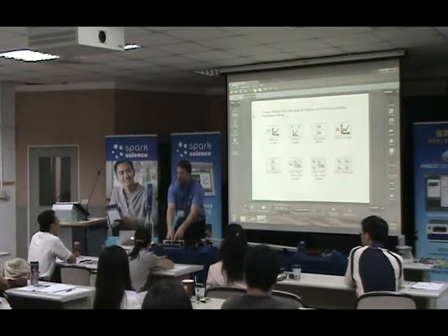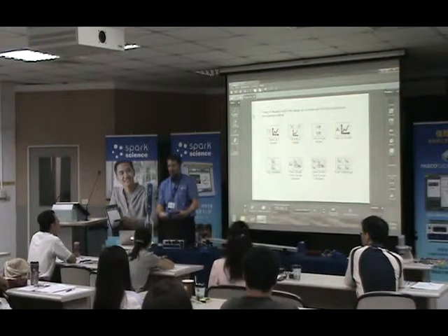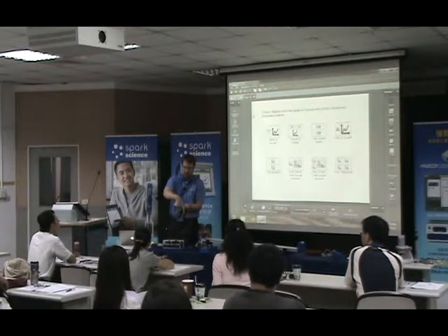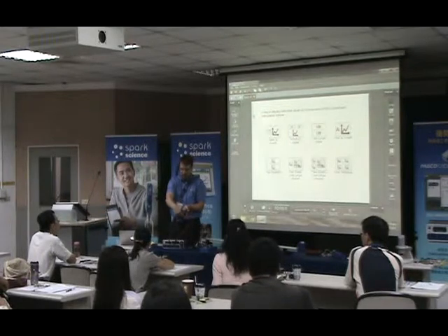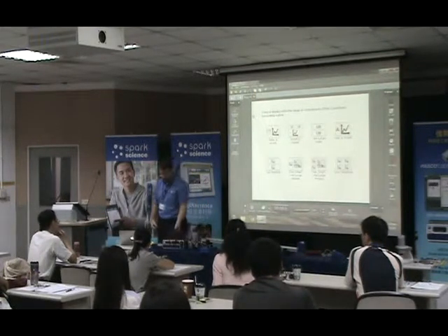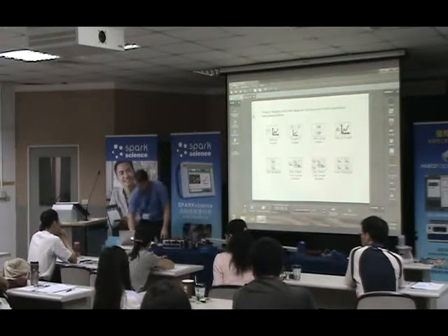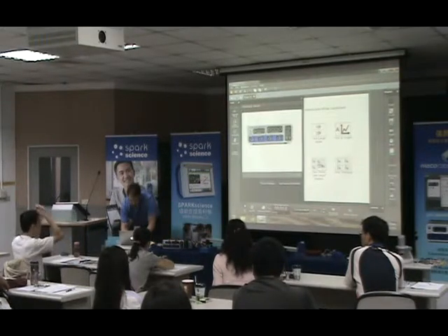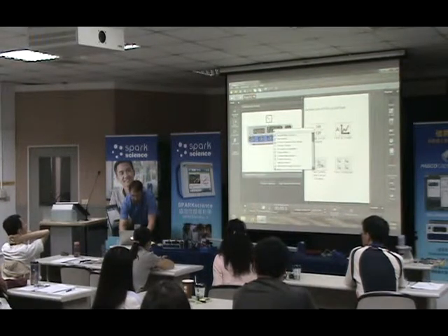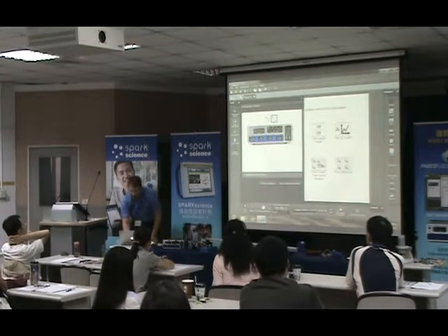And then these two things are voltage sensors. So I'm going to be measuring two voltages. One is going to be my source voltage across the whole circuit. So it comes in here and goes out here. The other is just the voltage across my resistor. Okay? So I'm just going to tell the 850 that I have two voltage sensors connected to it.